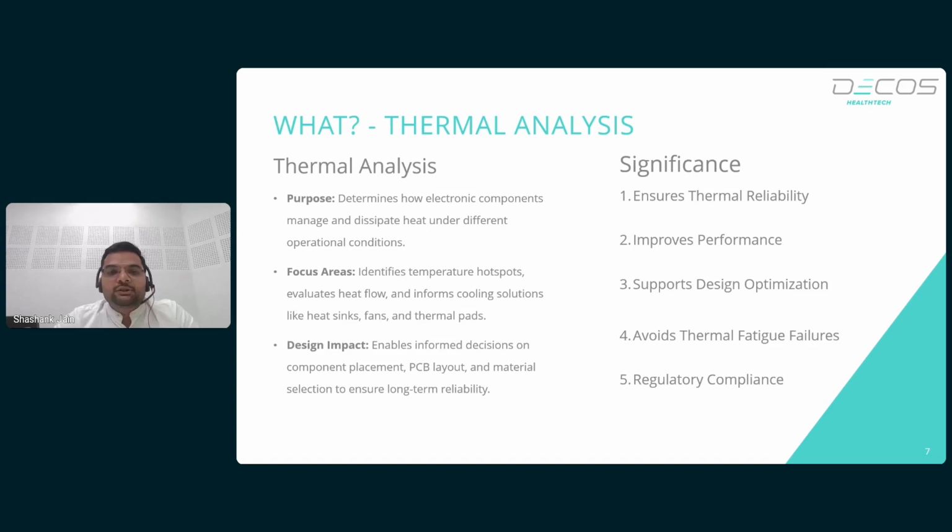So, first, it ensures thermal reliability by preventing overheating, which can degrade materials, components, and solder joints, ensuring system longevity. Then, it improves performance by identifying hotspots and optimizes thermal paths to maintain performance under all operating conditions. It also enables you to take informed decisions on whether you are going to use a heat sink, you are going to use a fan, you are going to create a ventilation design, and that too early in your product development. Okay, during the early stage of product development itself you can make certain decisions, right?